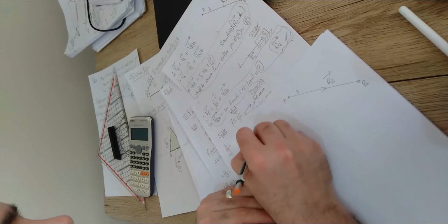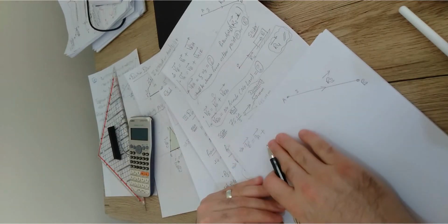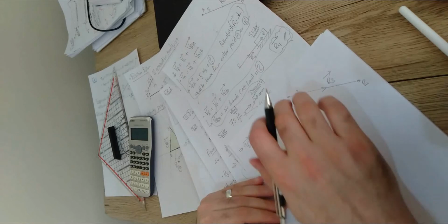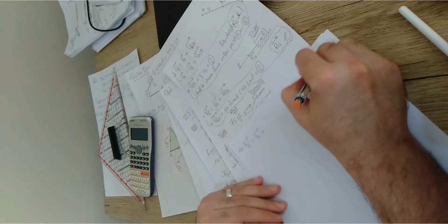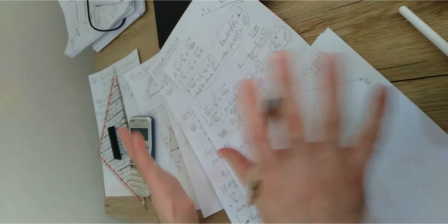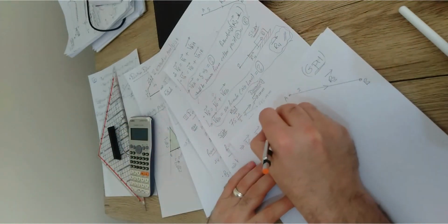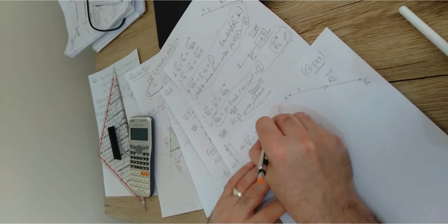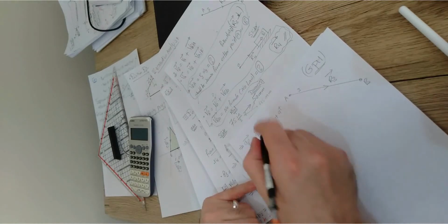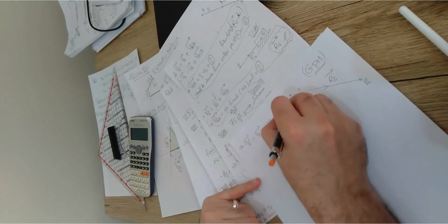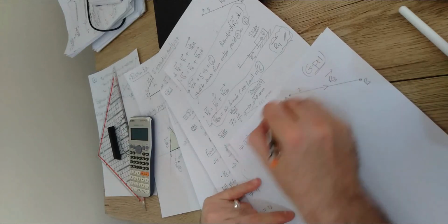AB vector equals AA vector plus, again, a normal component and a tangential component. Since this link is doing general plane motion, which is rotation and translation, there is no fixed point. Because of the rotation, we're going to have a normal component plus a tangential component, but these should be B relative to A, since we are talking BA, so B relative to A, BA vectors in this way.